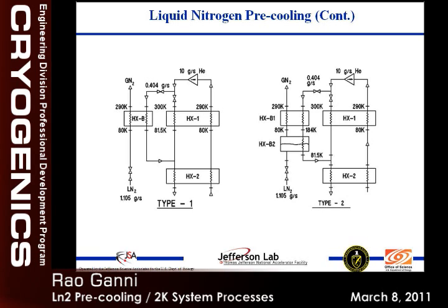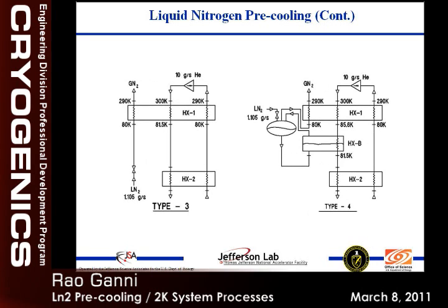The helium coming from 300K will cool halfway to 184, and 184 to 80, but this side will stay at 80K. This gives a big temperature difference, or makes this heat exchanger much smaller than doing it this way by spreading that, not taking advantage of the cooling curves. So there are differences in how to take advantage of the fluid properties in designing these types.